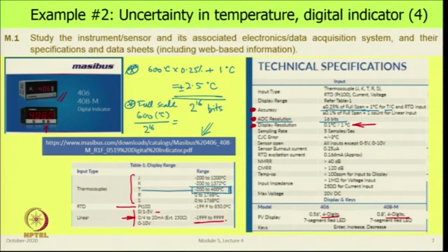So, as I was mentioning, many instruments in the real world which are used in process control would all have on the top of the instrument a transmitter which will convert the signal into an equivalent current signal and send it out.